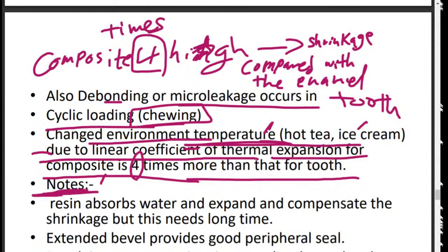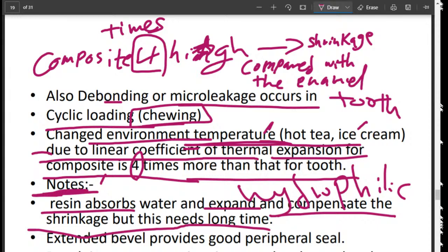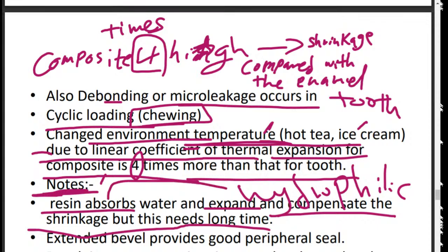There is a note here: resin absorbs water and expands and compensates the shrinkage. But this needs long time. Of course, this is talking about hydrophilic resin, which resists the shrinkage of the composite.